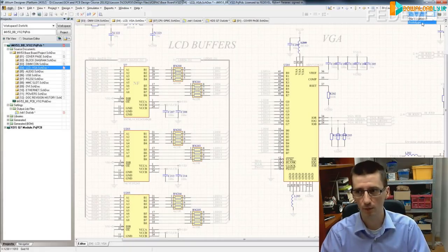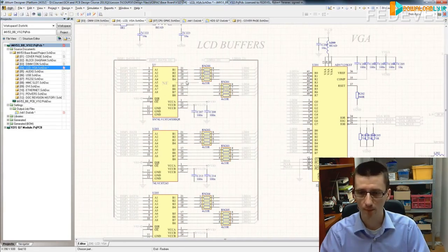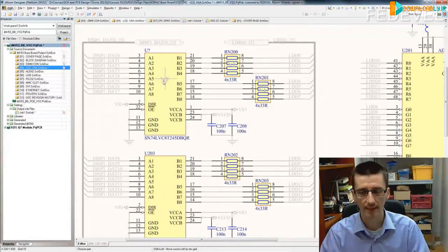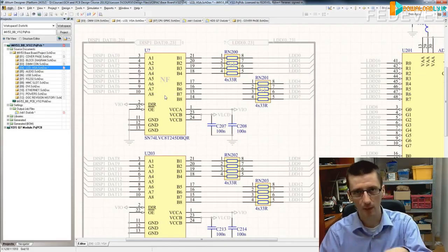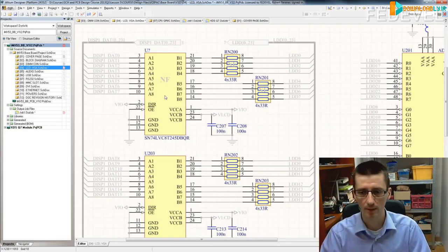Can you follow it? Okay. And now a button appears here. When I click on this button, I can visually find the component which I don't want to have fitted. For example, this one which I selected previously, and if I don't want to have it fitted in prototype, I just click there. You can see it's taking quite a lot of time to do it.